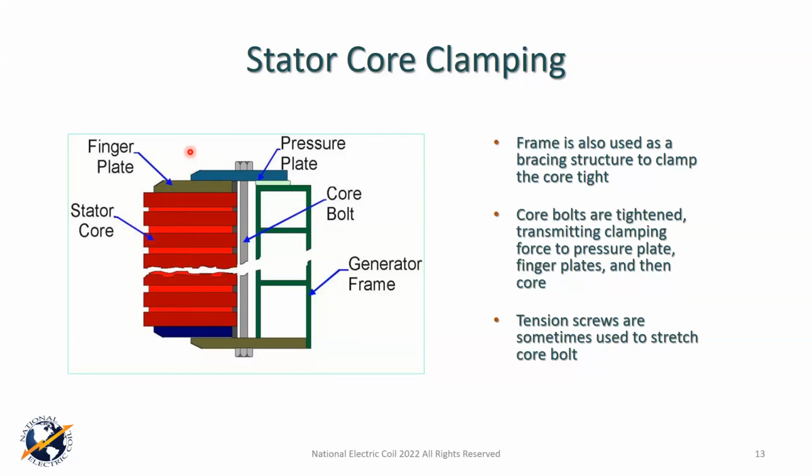On the other design with the through bolt that we're running down the middle, all we're doing is trying to sandwich this thing together. As soon as it starts to lose any compression, it's like a snowball going downhill. It just really accelerates its looseness pretty quick. And that's why in a lot of the older Westinghouse machines, there were a lot of efforts put into core tightening, and they came out with a bulletin called OMM 99, I believe, that dealt with using a special steel called Nitronic that was like a rubber band, but it was made out of steel, so they could stretch this bolt so it had more elasticity, so it gave some forgiveness.